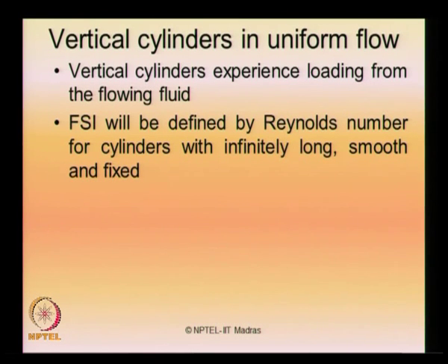But there is a basic assumption here that the cylinders are infinitely long and have smooth and fixed ends. If you have roughness, if you have the ends covered, or you have a finite dimension of the cylinder, for example in the case of a TLP where the pontoon lengths or the column lengths are fixed or smaller compared to the water depth, then all these concepts we talk about will get modified.